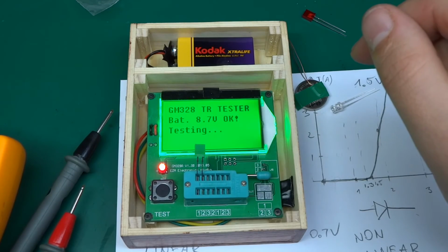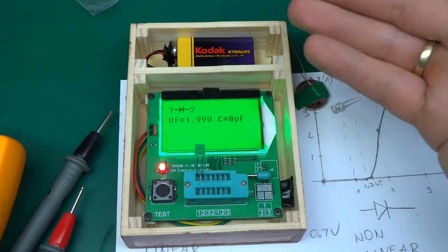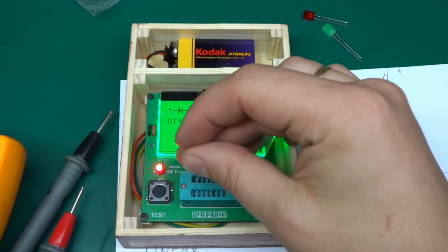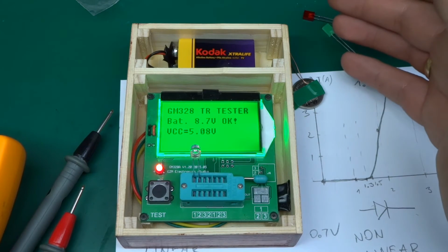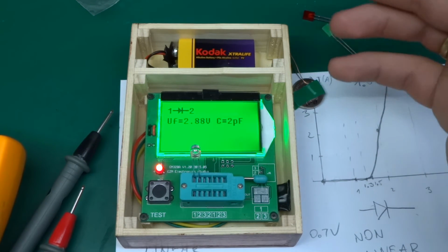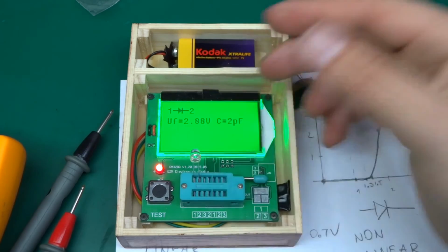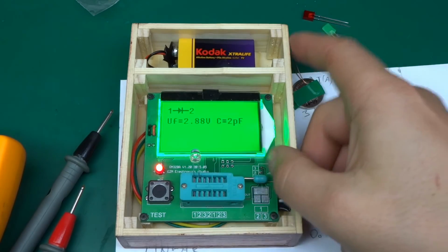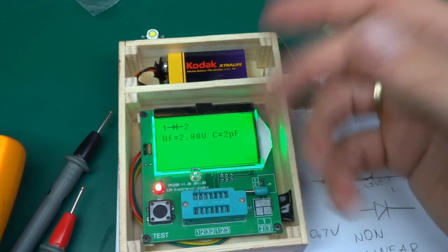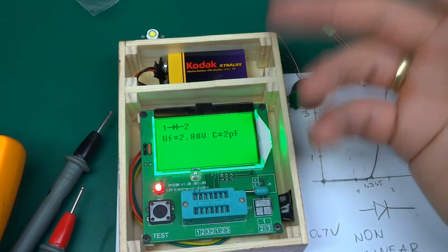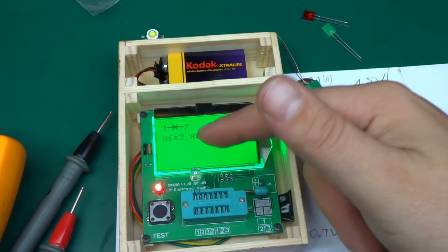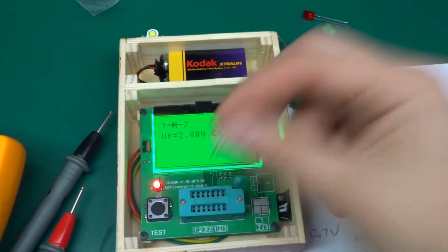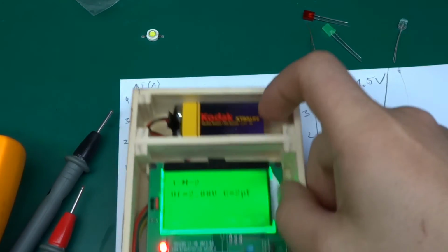And let's check this one. Yeah, it gives a few blinks because it's doing the testing. 1.99 volts, slightly off from the multimeter measurements, but it doesn't matter, I guess. One of them is wrong. Next one here, 2.88 volts. So you see, this is a new one, the blue one, and it's got quite a lot higher forward voltage, 2.88 volts. Now this will actually show you even higher voltages, whether your LED is working. So you can see that it's gone over that 2 volts barrier, and the multimeter was showing the over-range symbol over there.